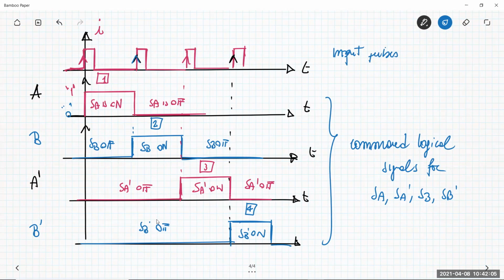Remember that if you change the sequence that I have here, you can have anti-clockwise rotation. This depends on another logical signal, the signal R, provided as input, which can be 0 or 1, depending on whether you want clockwise or anti-clockwise rotation of the motor shaft. Anyway, this is the sequence of logical signals you have.